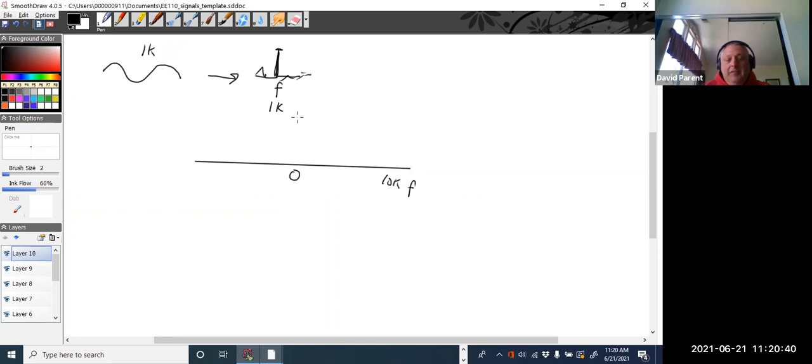That power spectral density function will take that noise and kind of smooth it out to give you an idea of what the shape of that noise is. So it'll average it out so that you're getting a smooth curve. And as I take that data and extract, I just curve fit to this pattern.